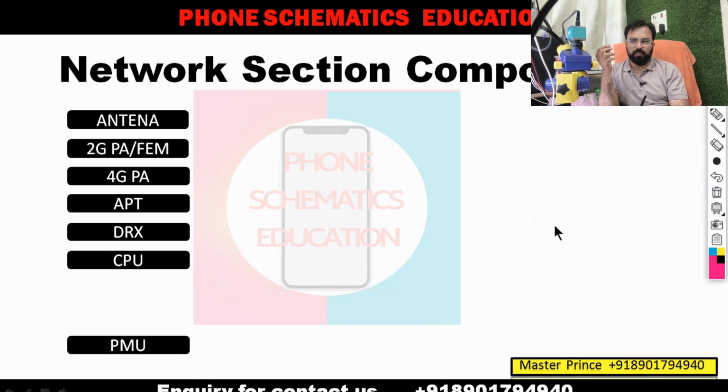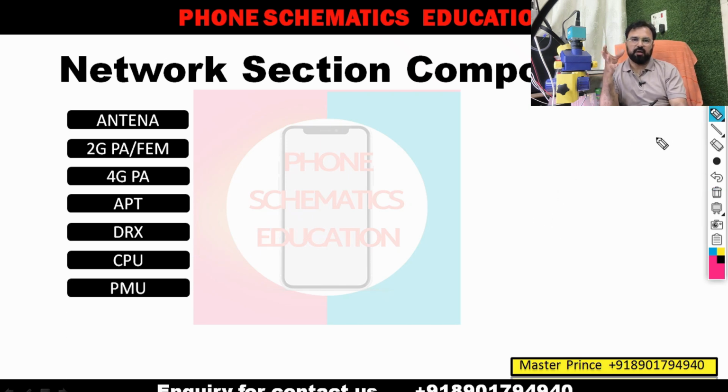Now, next one, PMU. The PMU is like the main power unit of your mobile phone. The network section has multiple chips, like your 2GPA, 4GPA, your RFIC, your DRX IC, your switches, filters. There are multiple, and every IC needs power to run. So your PMU creates the power for the network section. If any line from the PMU is open, your network does not work. I hope you get my point.